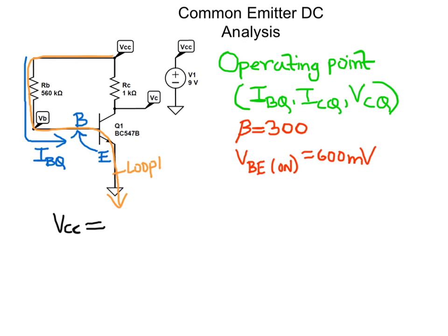I'm getting rid of some of the clutter to make more space. So we have found out the quiescent base current equals 15 microamps. We know that the quiescent base current IBQ will be amplified by a factor of beta by the transistor Q1. This amplified current would flow through the collector resistance RC into the collector node of the transistor Q1.